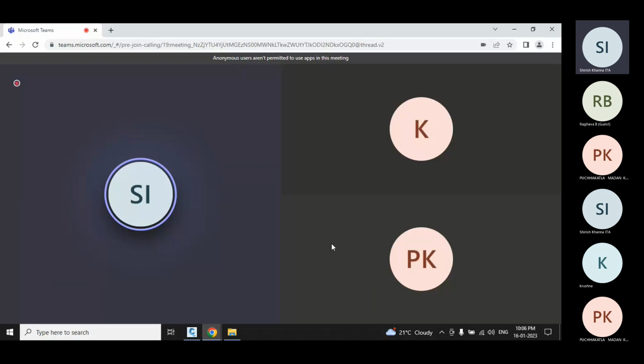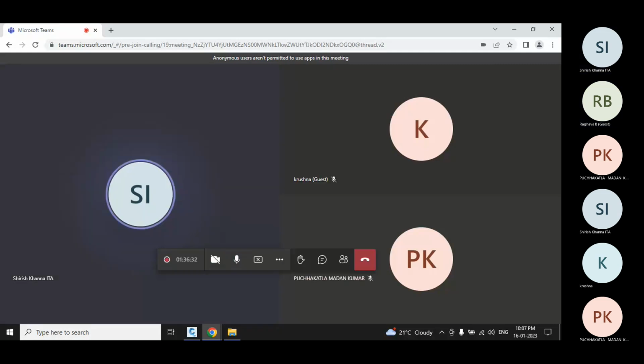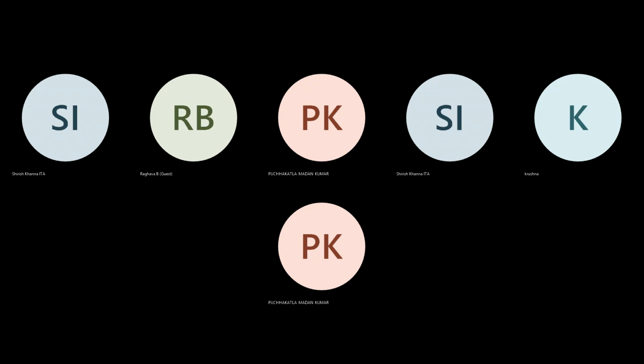No, sorry. First you have to attach the terrain file, and then merge these two with the help of model. You have to create a 3D view. Then you have to go for profile model, the actual profile. Then you can create a vertical alignment. Okay, sir. Any other doubt? No, sir.